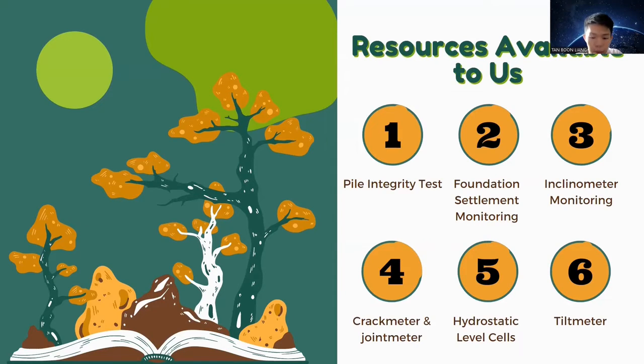For the first one, the pile integrity test can be applied in order to determine the potential of the pile to have defects. The foundation settlement and inclinometer monitoring can be used to measure the displacement in the ground and in structures that lie below the ground.